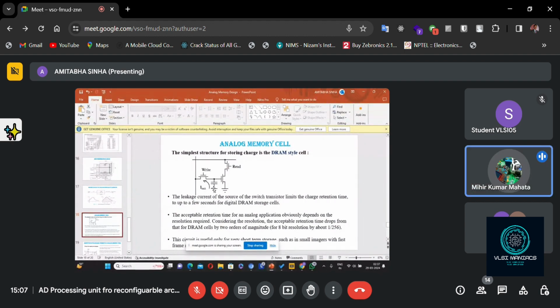Then, sir, when I'm enabling read, that transistor is switched on, and as there is positive charge across the gate, the downward transistor is also switched on. Now the source of that transistor is connected to ground, so ground potential will come across the end point, that means the vertical line, isn't it, sir? Horizontal line, sorry. Okay, you can think in that way.